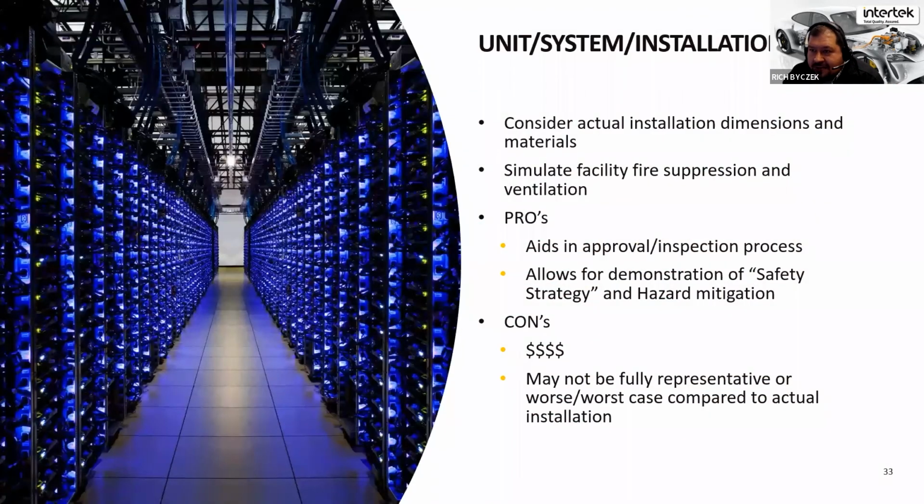So that brings us to unit or system level installation tests. And from a building codes standpoint, this is considered the best method. We have to simulate the actual environment. It is potentially the most representative of an actual installation, but it's very difficult to implement in a lab environment. It, of course, costs a lot because you're essentially going to reproduce the entirety of an installation, which may be a one-off installation. So from a feasibility standpoint, this is probably the worst case for us.